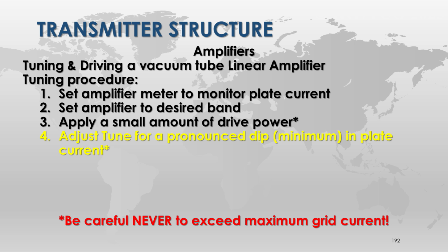Now, it's the grid of the tube. What that statement is based on is the idea that the grid is a very fine piece of wire inside the tube. What happens when you make a really tiny piece of wire and you add current to it? Well, it depends. If it's properly designed, you have a light bulb. Well, it's true, but what they're talking about here is the fact that wire is current limited, and you'll turn it into a fuse if you overcurrent it.